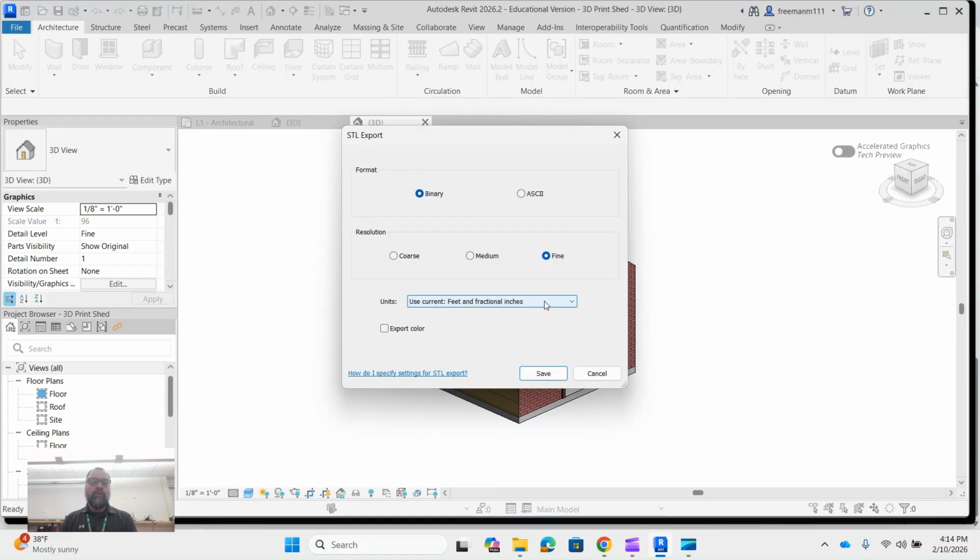What you want to make sure is that if you are planning to have a finished product that uses multiple parts, you are exporting them in the same units, and when you scale them in your slicer, that they are scaled uniformly.